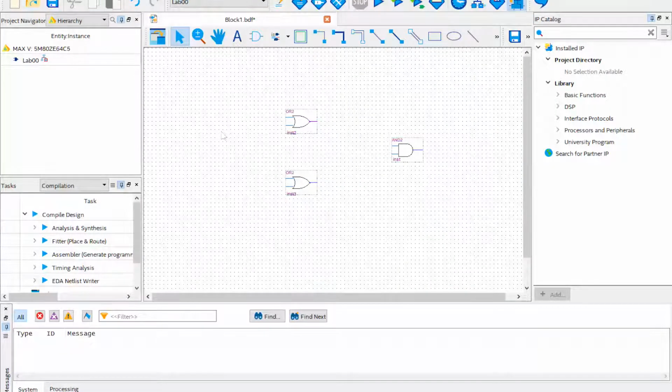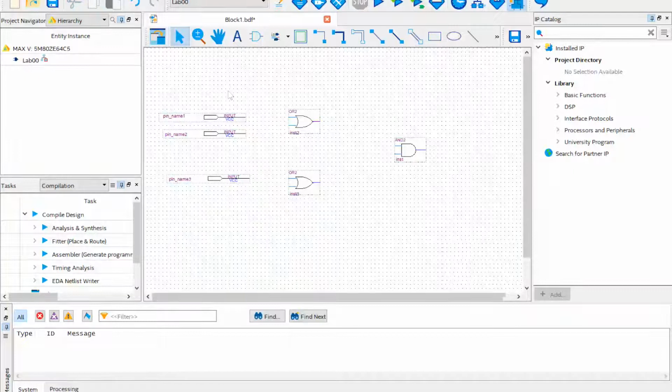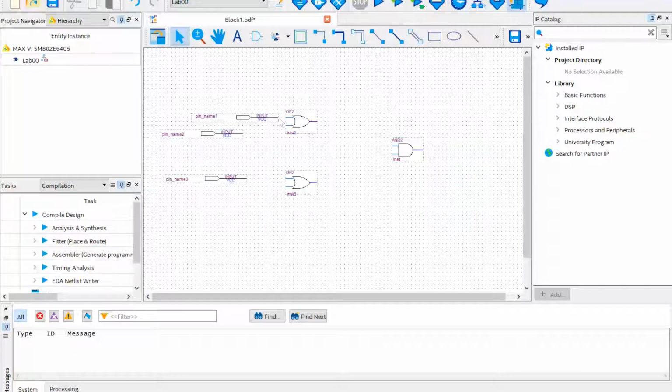All right, we obviously need inputs and outputs because the circuit's useless without that. You can click up here, inputs and outputs. That makes more sense to me. You can just click input. We'll put A there, put B there, and we'll put C there. I always like to line things up as best I can. Sometimes the software just works against you. One of the mistakes I've seen students make is to put these really close together. The only points that it's going to connect are either at the wire, at the gate there, or at the input right there.